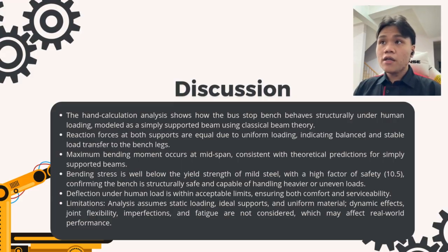Limitation. The analysis assumes static loading, ideal supports, and uniform material, so dynamic effects, joint flexibility, imperfections, and fatigue are not considered, which may affect real-world performance. And that's all from me.